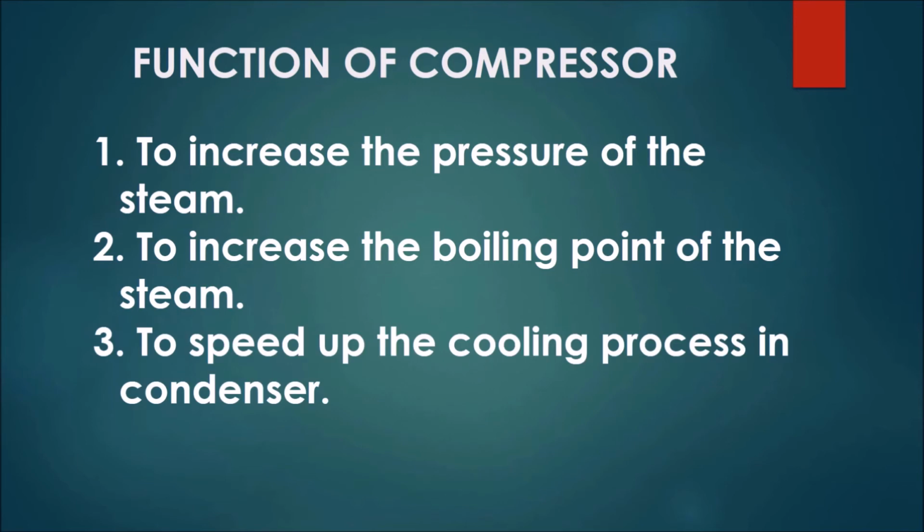The third function of compressor is to speed up the cooling process in the condenser. As the steam passes through the compressor, high pressure steam and high boiling point steam are produced. As the steam passes through the condenser, the cooling process of the steam from high temperature to low temperature and the phase change of the steam from gas phase to liquid phase will be much faster as the boiling point of the steam is increased.